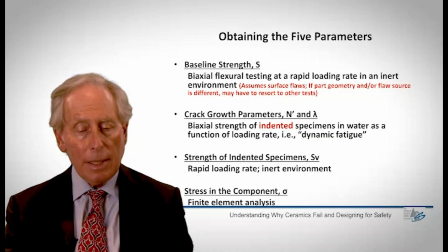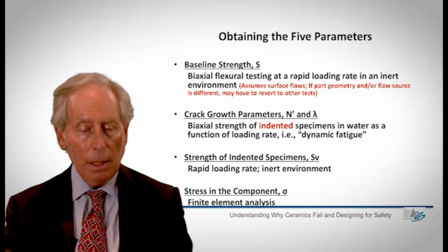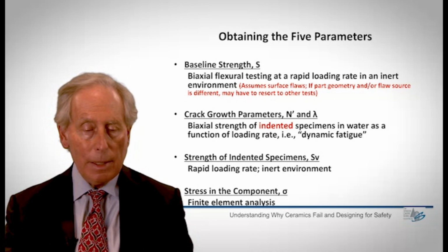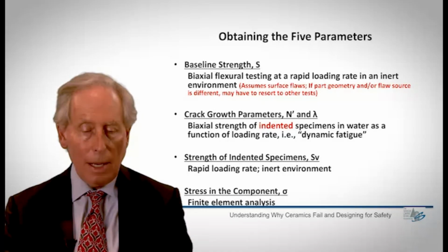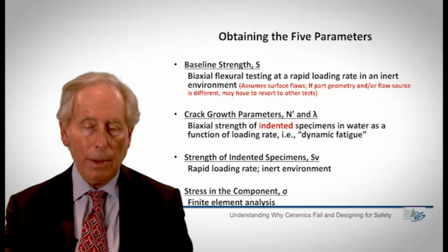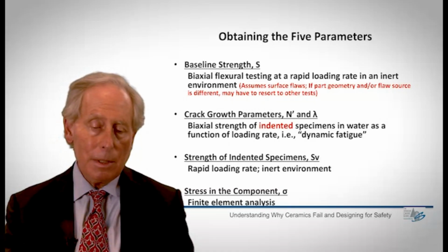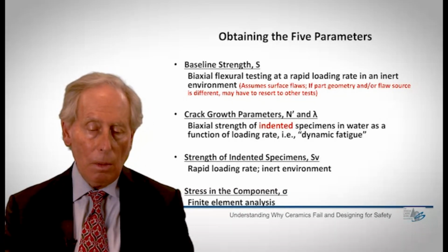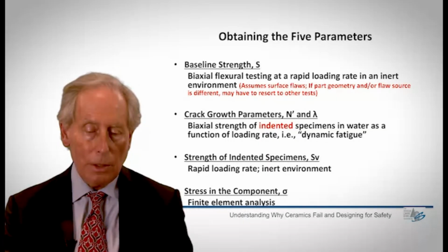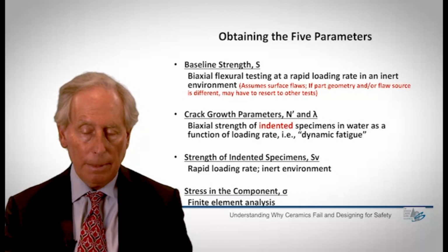The strength of the indented specimens, S sub v, is obtained in exactly the same way as I did the baseline strength. I do it on indented specimens instead of as finished specimens, but in an inert environment at rapid loading rates. And then the stress in the component, typically I would do by a finite element analysis. Sometimes I think I know what that number might be, but one would like to do some quantitative values. So you could pick a different stress in the component if you know that in a different way.